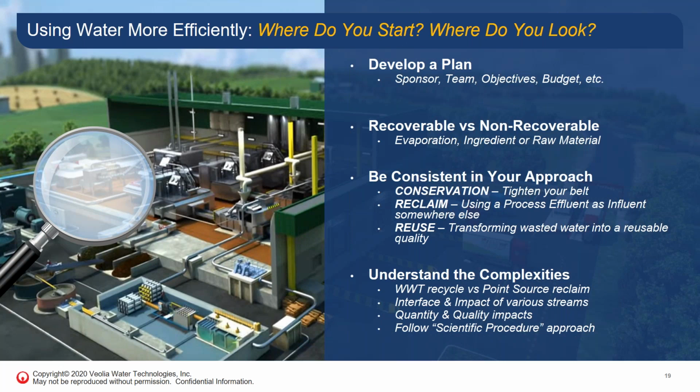Thirdly, be consistent. Go through the conservation, reclaim, reuse checklist for every water stream that you study. Tighten it up first, look where you can reclaim it second, and then look lastly whether you can reuse it by transforming it into a different quality water.